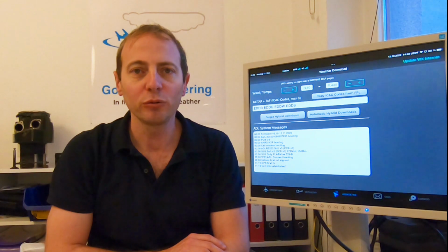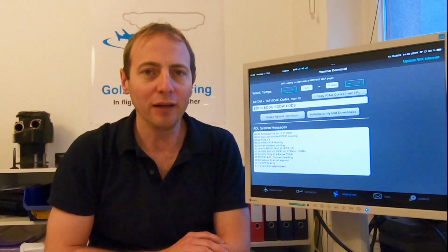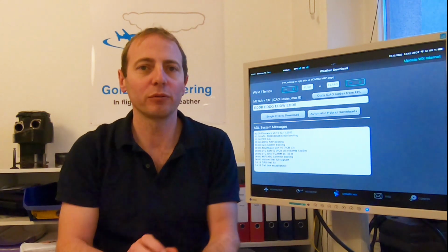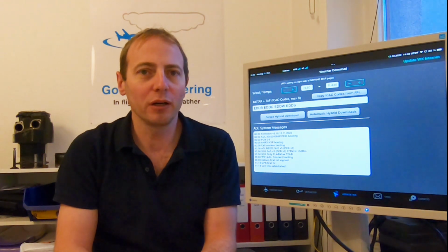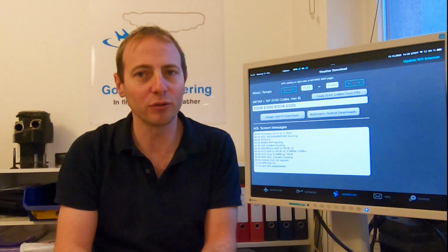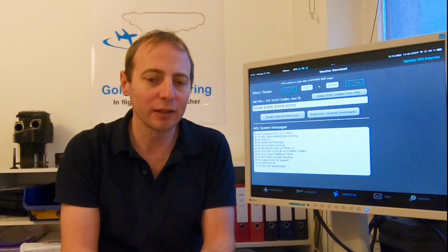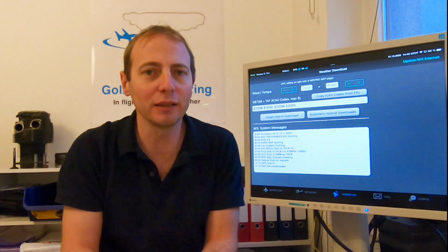The next step is to download any weather using the ADL device, so there's actually anything which can be transmitted to the Garmin avionics and displayed. So we simply do a normal weather download with the ADL device. We have an ADL 200 in that case, so it can actually download the weather over the 4G LTE network.